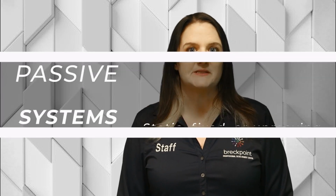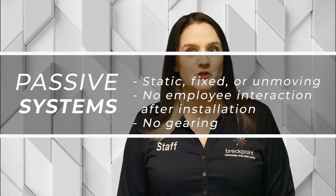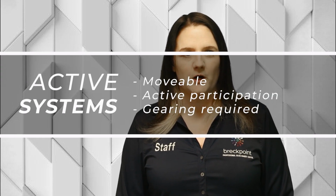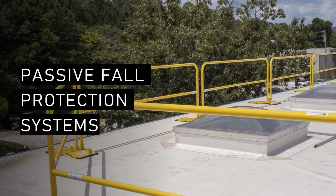Now that we understand the risk of working from heights and the fall protection trigger heights, let's review the different types of fall protection systems. There are two basic fall protection systems. Passive systems encompass all protective measures that are in essence static, fixed, or unmoving. There is no human interaction with the system after installation, and there is no need for personal protective gear. Some examples include guardrails, safety nets, floor covers, etc. Active systems, on the other hand, involve active participation of the worker, are movable, and require the use of special gear. Let's review some passive systems.